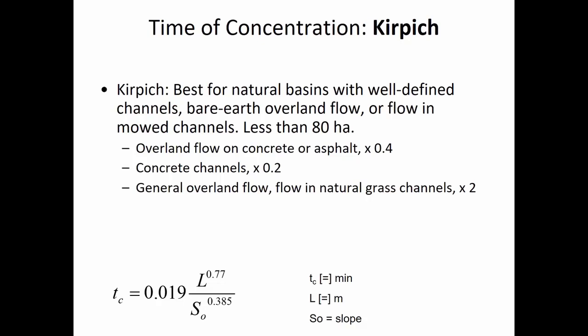So if we were looking for thresholds, probably overland flow is maybe just a few millimeters. Any more than a few millimeters and it's going to naturally become shallow concentrated. Shallow concentrated flow is from a few millimeters to maybe 1 or 2 centimeters.